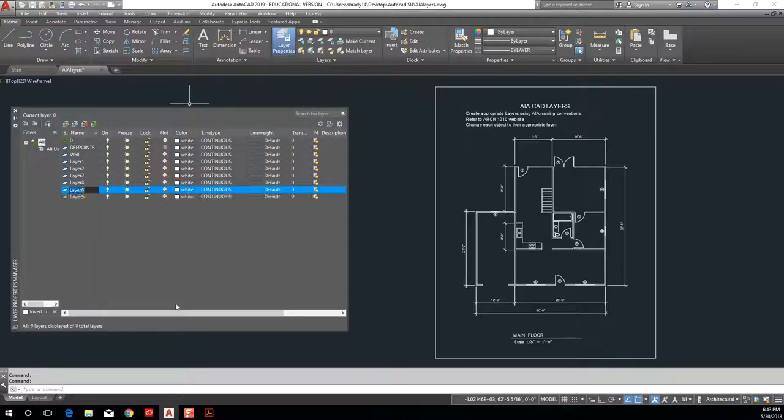It's a problem when you have set one layer to not print and then you copy it 18 times, and you're drawing on those layers, none of them set to print. You're new at AutoCAD and you don't realize that, and you draw for hours. Then you go to print and all of a sudden nothing shows up on your page. I like to point that out because it's the number one mistake beginning students make.